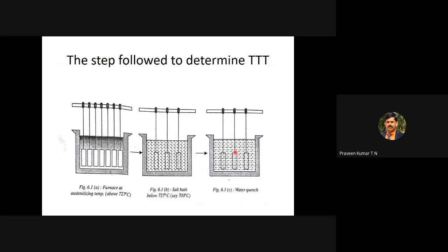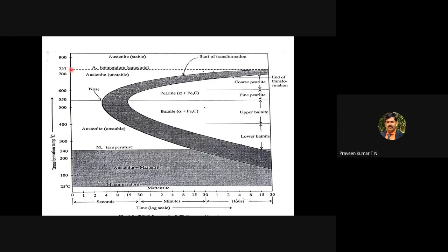What you did in your lab is, you heated the steel above 727 degrees Celsius. Then you did not soak it. You removed it from this process. Straight away you quenched it in the water. Quenching is nothing but a sudden cooling process. Most of the time you put it into the water. We bypassed this stage. Then we'll get a new microstructure, that is martensite.